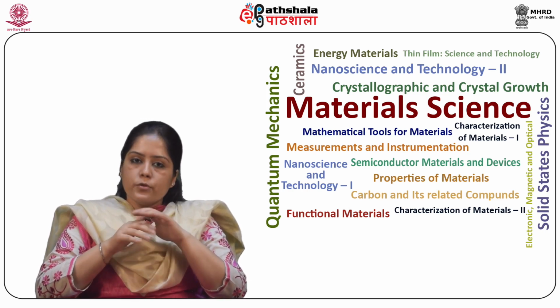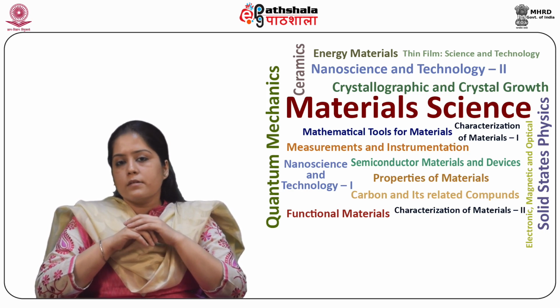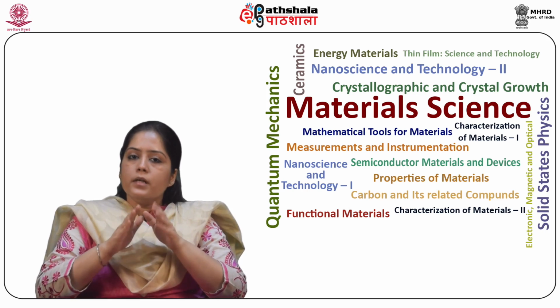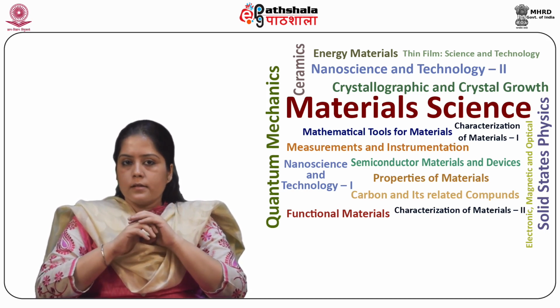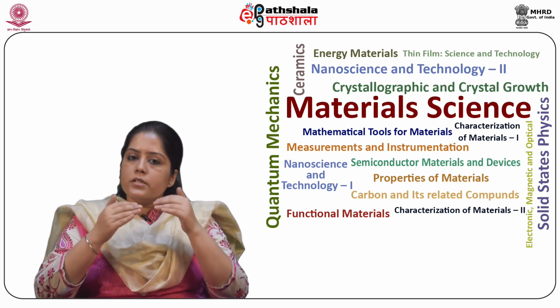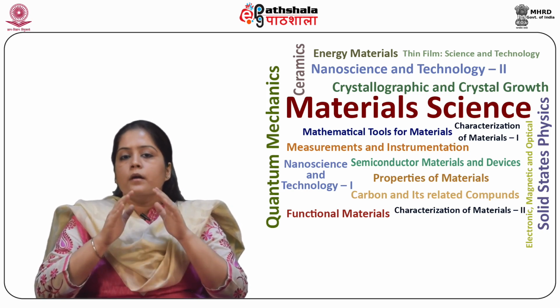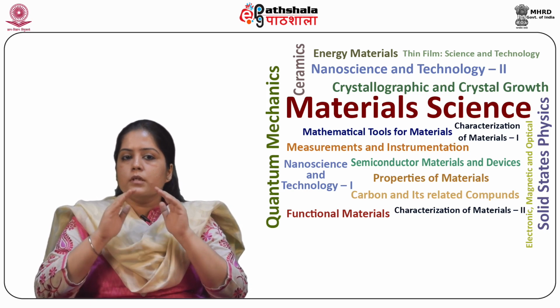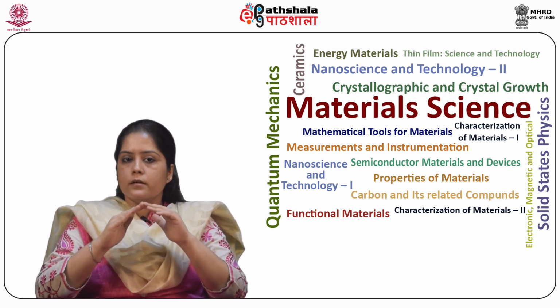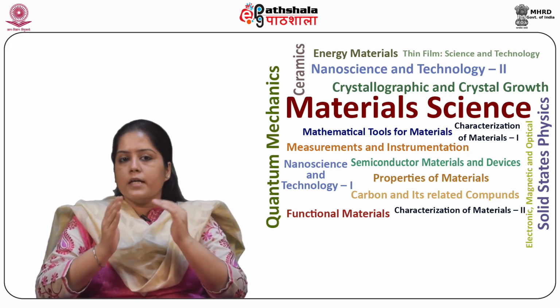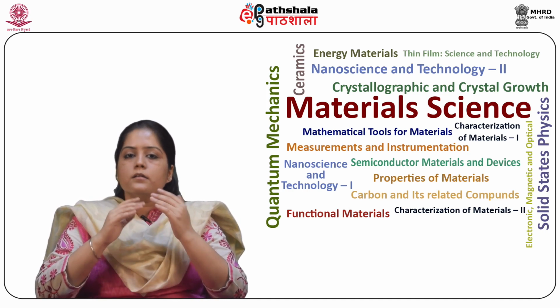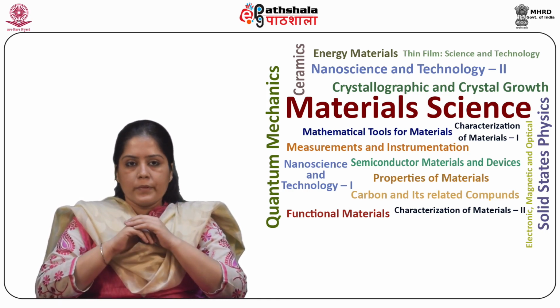The major contribution to the series resistance RS comes from the bulk resistance of the semiconductor material, the metallic contacts and the interconnections, carrier transport through the top diffused layer, and the contact resistance between the metallic contacts and the semiconductor.